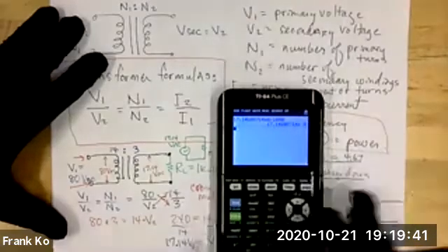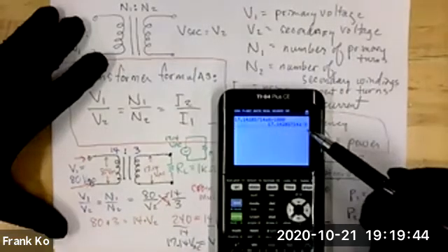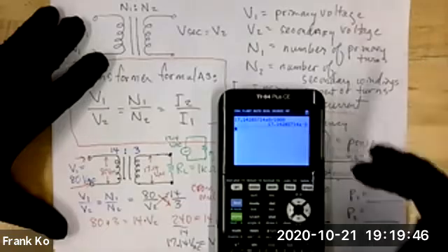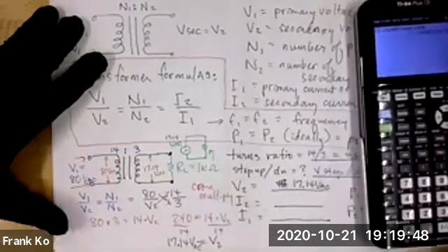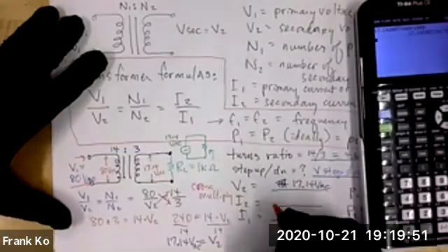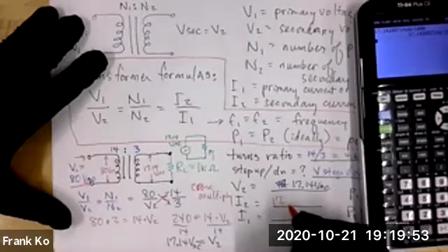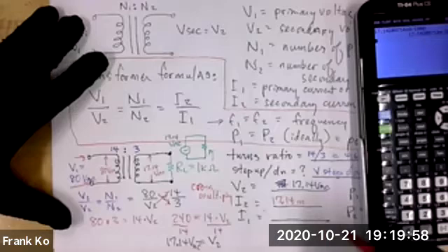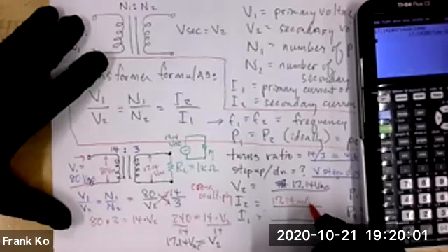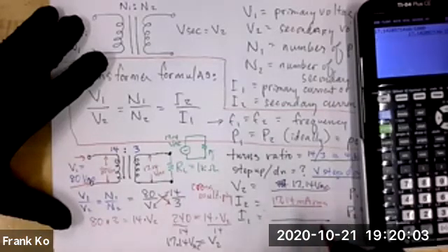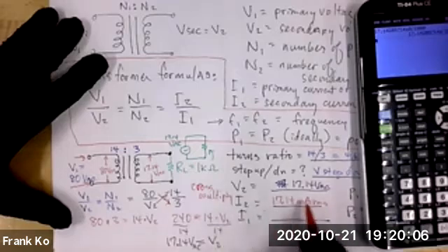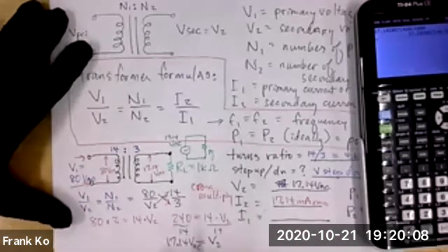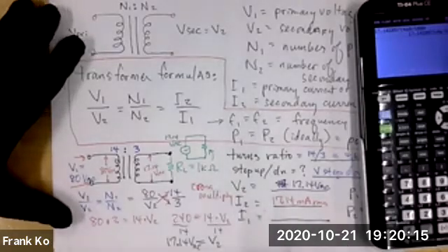Yes, right? Isn't there an exponent of -3 at the end of the line? You divided it simply by 1,000, so it'll be 17.14, same numerals, except it's going to be milli, because milli means divided by 1,000. Milliamps RMS. Okay? Is everybody all right with that secondary current? Was that easy to calculate? How do I find my primary current?